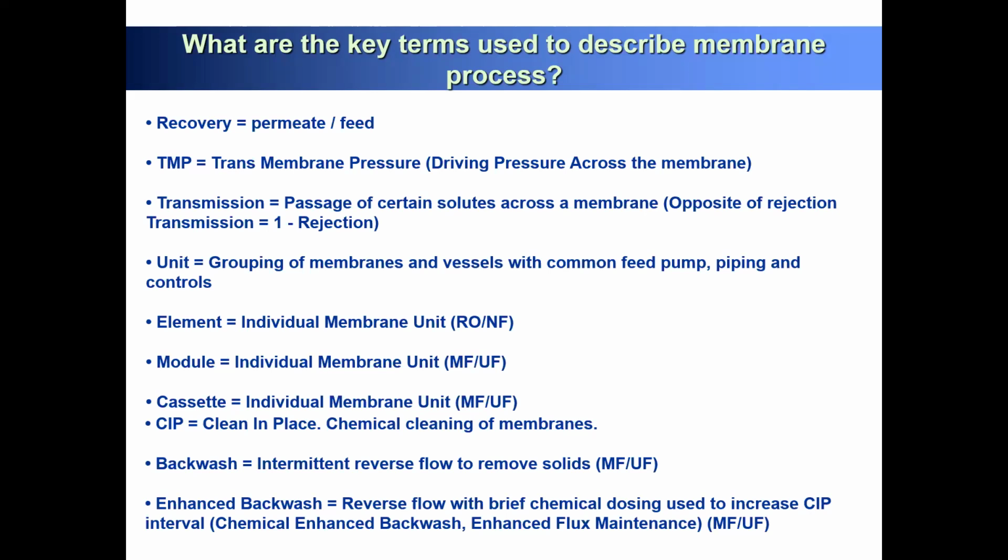Also, transmission is the exchange of certain salt across the membrane. So we have to look at the detail, your concentration. So one of the assignment questions is about boron concentration. So we have boron, which is a harmful compound, and the seawater contains boron concentration of 10 milligram per liter. So we like to reduce it to less than 0.5 milligram per liter. So